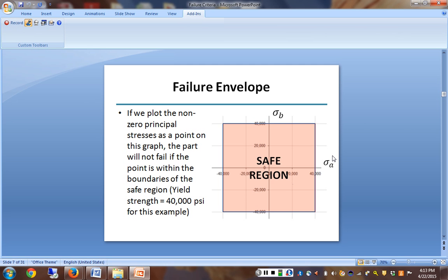So this is a graphical representation of the failure criteria. This maximum principal stress one is just saying, am I more than or less than? So that's why it's a constant in every direction. Just, did my tension get that big? Did my compression get that big?